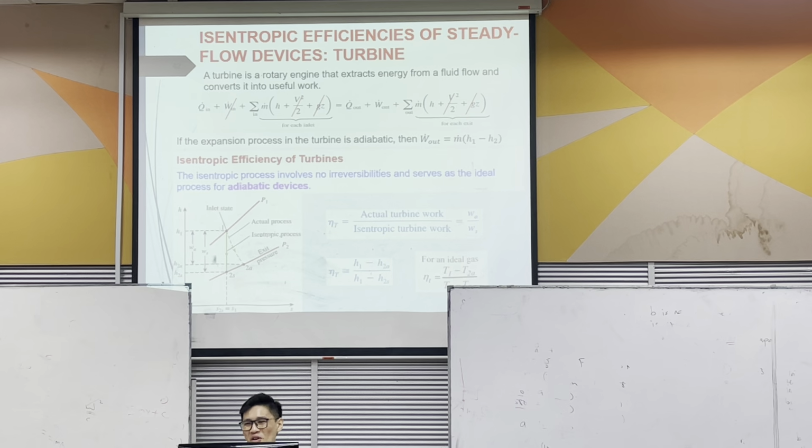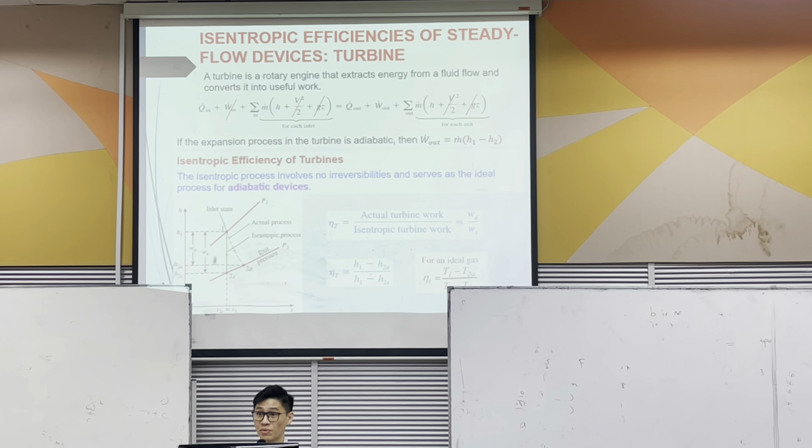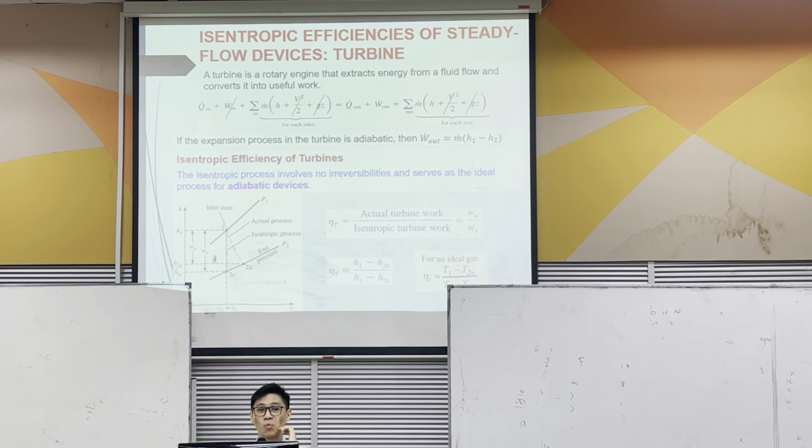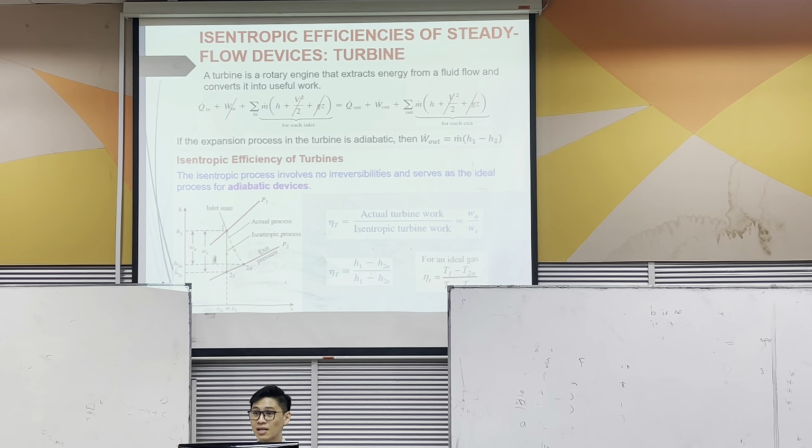Okay, so now let's look at this derivation first. Let's establish something first. We call isentropic process a process that doesn't involve heat transfer, right? Adiabatic process, so you don't have any heat loss or heat gain. So obviously, things like an evaporator, boiler, or condenser cannot be isentropic processes, because those heat addition or heat rejection processes primarily involve heat transfer. So we are talking about processes that usually are not supposed to involve heat transfer, like the turbine in this case.